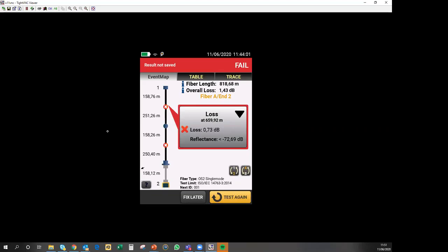beautifully this morning. Now at this point, if we were in the field, we would clean the end faces of the smart loop fiber, which is something that I can do, and we would try again. However, that would require an additional 40 seconds or so, and I don't think we're going to add an awful lot from this. Please just accept that bidirectional average is the valid test result. And the net result here is that we have a fail in our test result, primarily because we couldn't see the connectors of the loopback fiber.